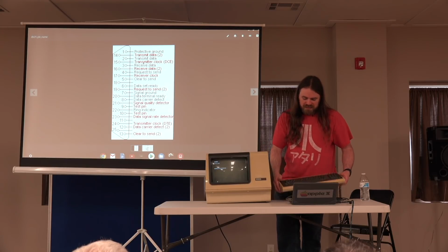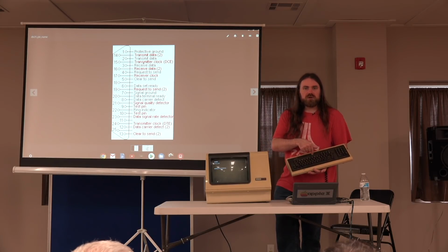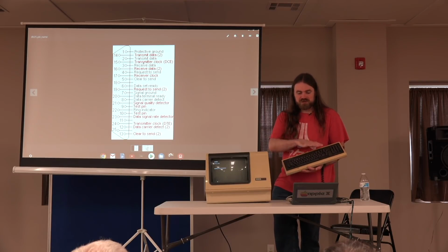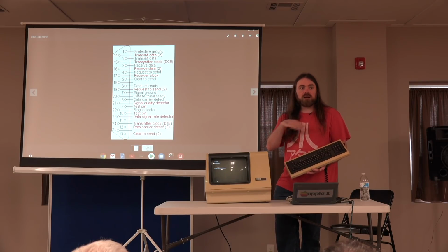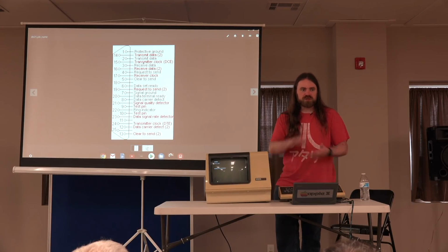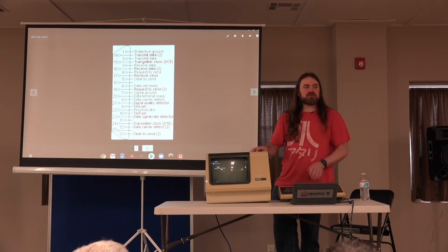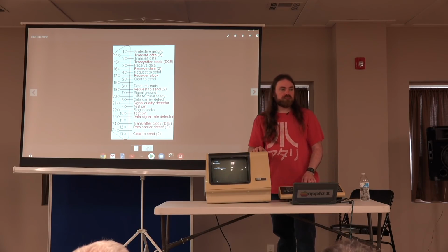Usually when you take a key off, there'll be a spring underneath the key, and that'll kind of clue you in. You can also take the circuit board out and flip it over. You'll see no contacts for the switch contacts. The circuit board is screwed to the frame with a whole bunch of screws, but there are no wire leads coming through. Lots of novices see those intertwined traces on the keyboard and assume, oh, I can just short it to see if it works.